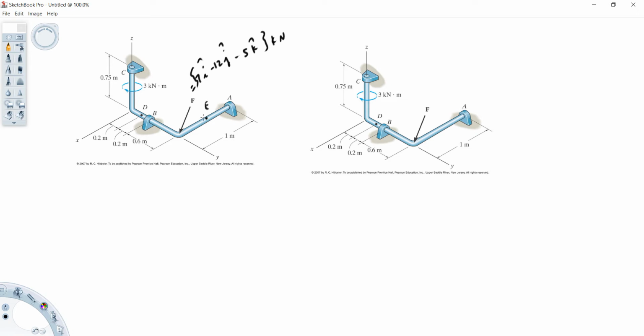Alright, I would start this, like most of these problems, by dealing with the reaction forces. One thing to take note of is, if we had the reactions at A, a free body of this piece of it would be very, very simple. As we take a look at this structure, it is designed to apply forces this way and this way, but not this way. So this C here, we're definitely going to have a CX and a CY.